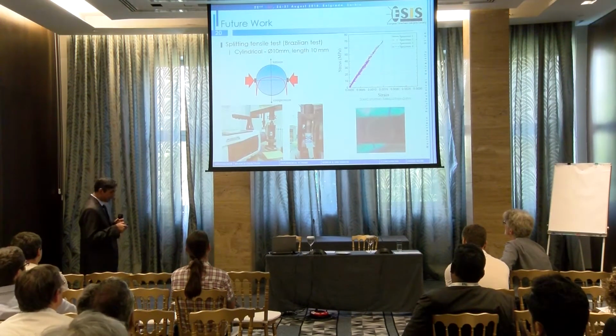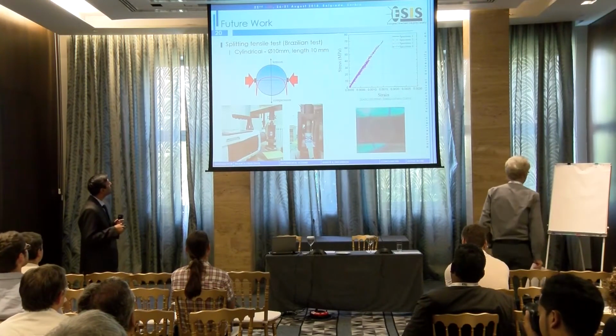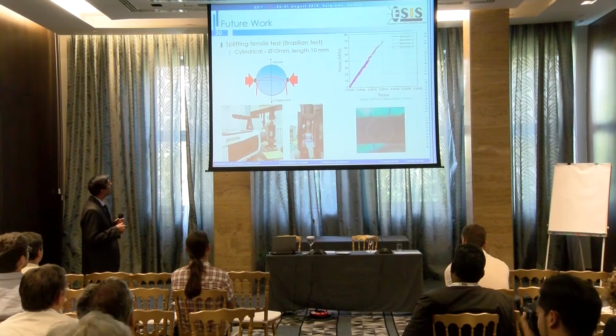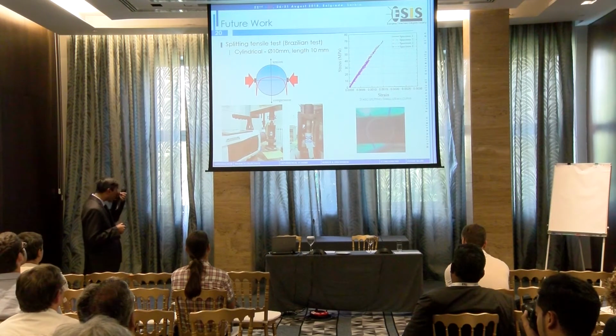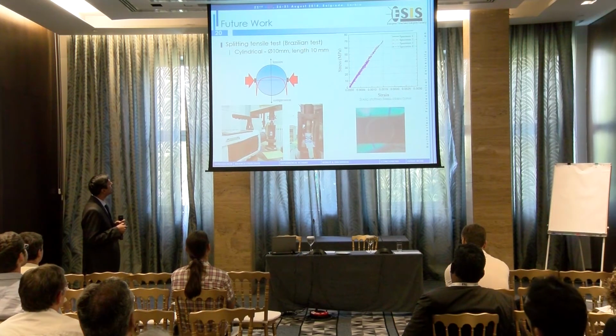As future work, because we have studied just the compression part, studying its tensile behavior is in progress. So far we have conducted the static tensile test. This is based on the famous Brazilian test. The concept is that the 2 surfaces in contact with the fixed bar and the moving bar are in compression, but the internal is in tension.